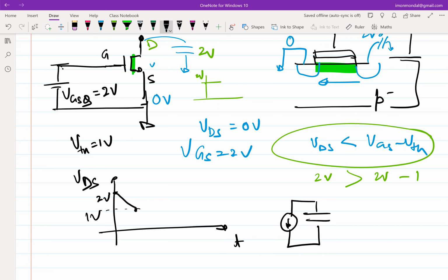Now, if that had been a pure resistor, I could have said time constant and it goes down with all those things. But now it's not an exact resistor. So you will see some profile, but this profile will not be exactly equal to a first order discharge, right? So maybe it goes like this, and eventually it will go to 0. Asymptotically, it will go to 0. So at steady state, your VDS will become 0, right? Okay, you had a question?